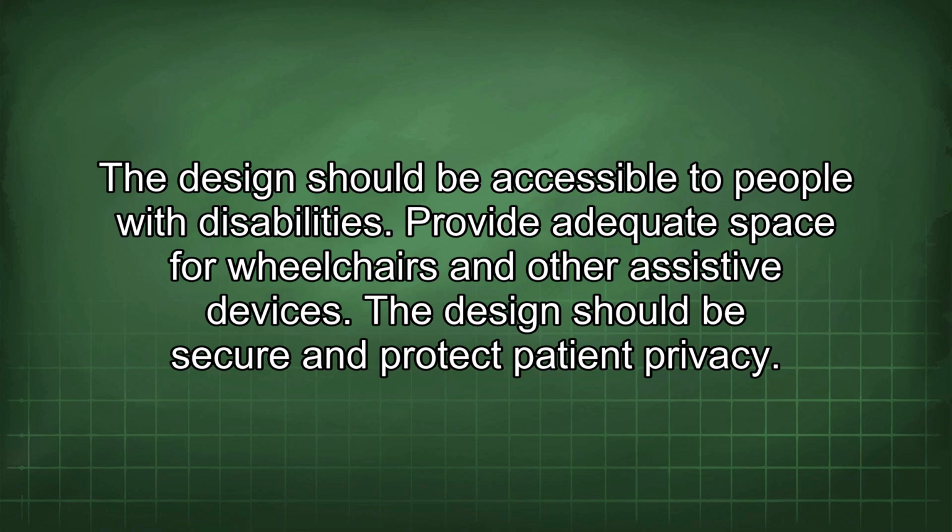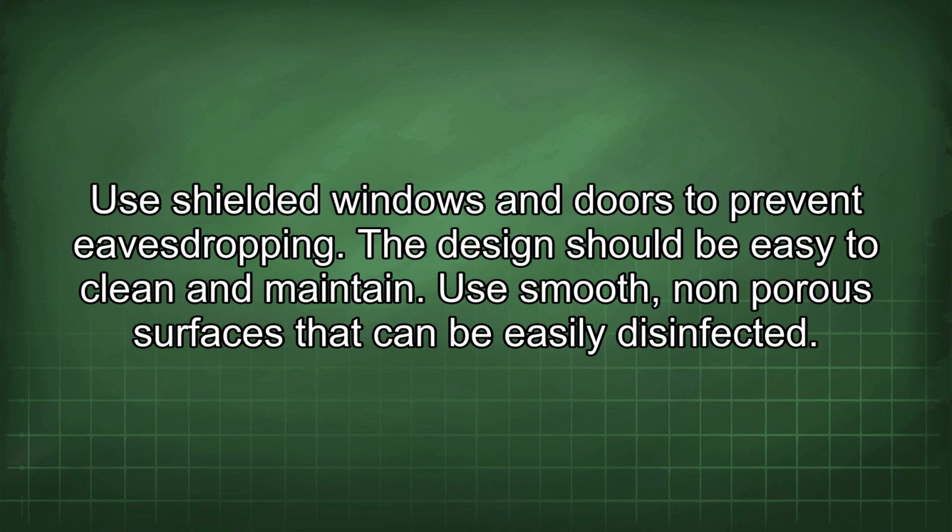The design should be accessible to people with disabilities. Provide adequate space for wheelchairs and other assistive devices. The design should be secure and protect patient privacy. Use shielded windows and doors to prevent eavesdropping. The design should be easy to clean and maintain. Use smooth, non-porous surfaces that can be easily disinfected.